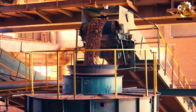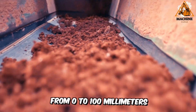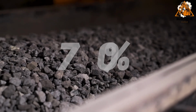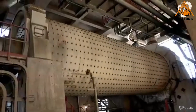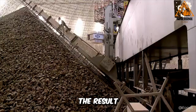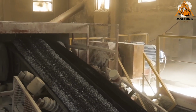The clay to be used is processed in special roller crushing systems, crushed to the size of granules from 0 to 100 millimeters. The obtained composition is further sent to the mixers for further soaking. This creates a slurry with a moisture level of about 70%. The components included in the mixture are mixed and pulverized using a specified percentage of moisture. The result is a charge with a moisture level in the range of 30 to 50%.